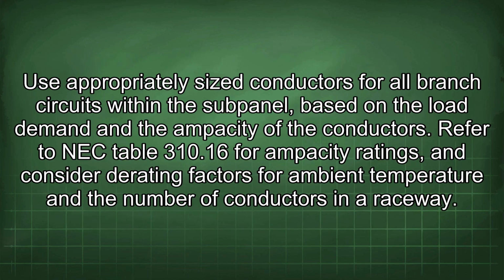Use appropriately sized conductors for all branch circuits within the subpanel based on the load demand and the ampacity of the conductors. Refer to NEC Table 310.16 for ampacity ratings and consider derating factors for ambient temperature and the number of conductors in a raceway.